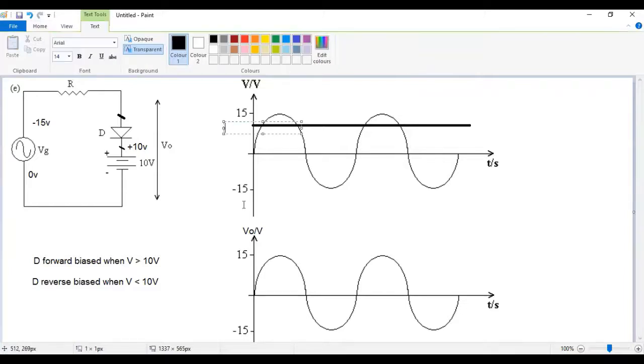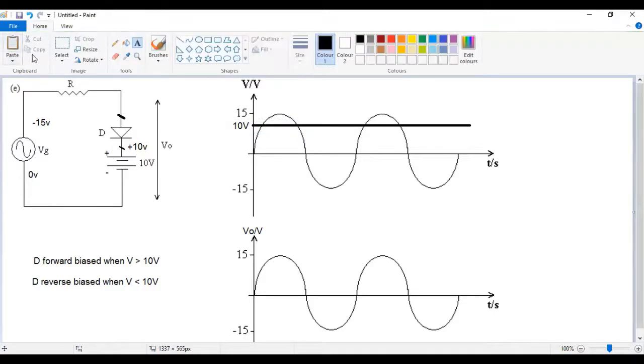So you're going to draw this line there on your waveform. This is a 10 volts line. And then next step here, you're going to draw drop down lines like this. I'm just going to do that in thinner lines. So these are important points because this is where your circuit is shifting from one state to the other, because the diode would conduct or not conduct.